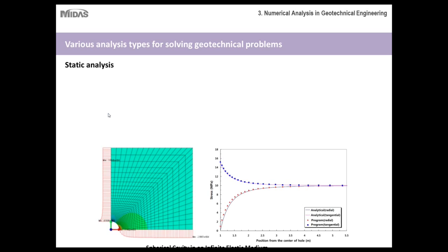So first, let's discuss static analysis. One of the main characteristics is that it's a final stage analysis without construction stage. So for projects that don't have complex constructions or excavations, you can just model the complete project itself and analyze the effects of the loading on your soil.